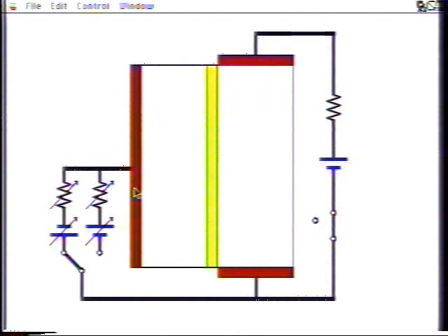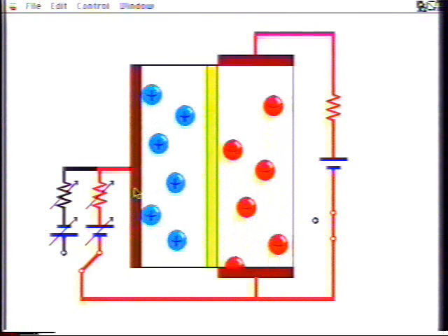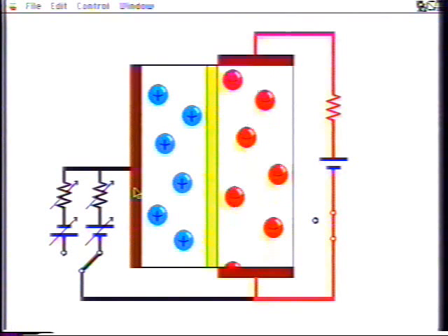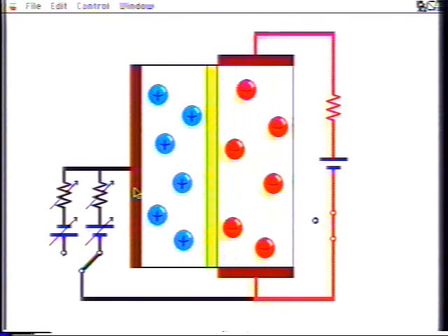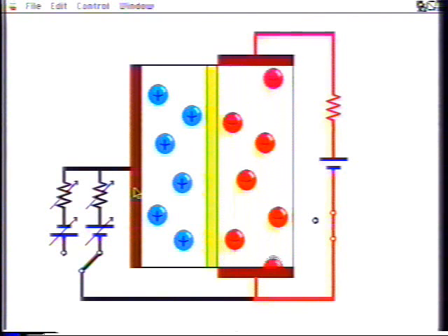Let's repeat the off-on-off sequence with the output circuit closed to begin with. Initially, no current flows. The FET switch is off. It's turned on by placing positive charge on the gate. Note that gate current flows while the gate is being charged, but stops once the charging is complete. However, the drain current continues after the gate current has stopped.